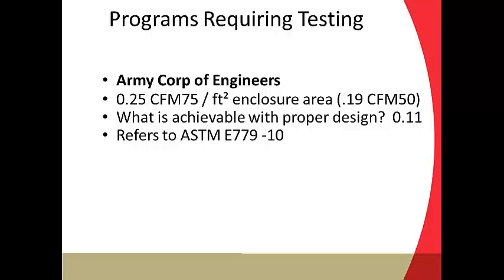It refers to E779 as a testing protocol. They've adapted it a little bit. They're referring to ASTM E779 requiring 10 data points instead of 5, and they give you a little more leeway as far as what temperatures, weather conditions, and wind conditions you can do the test on.